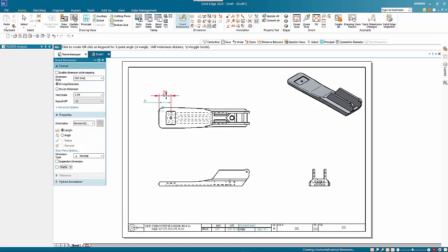For the majority of my dimensions, I'm going to use the ISO millimeter one, but if I use that on a radial dimension, the text is set up to align with the dimension, so I prefer to see a dimension hanging off in this sort of fashion, and it just reads better for my preference.